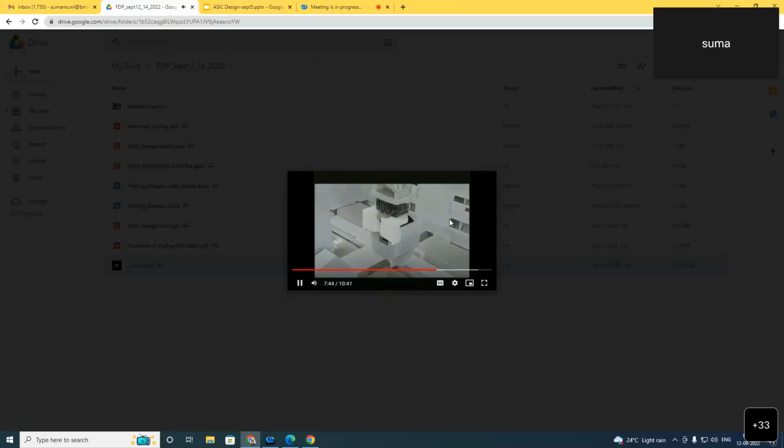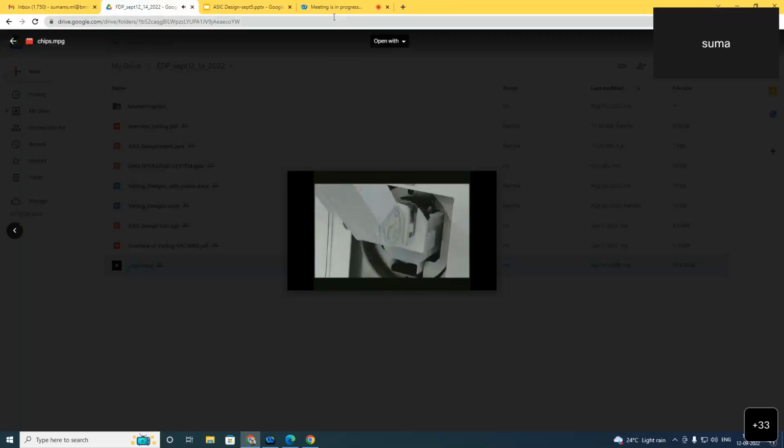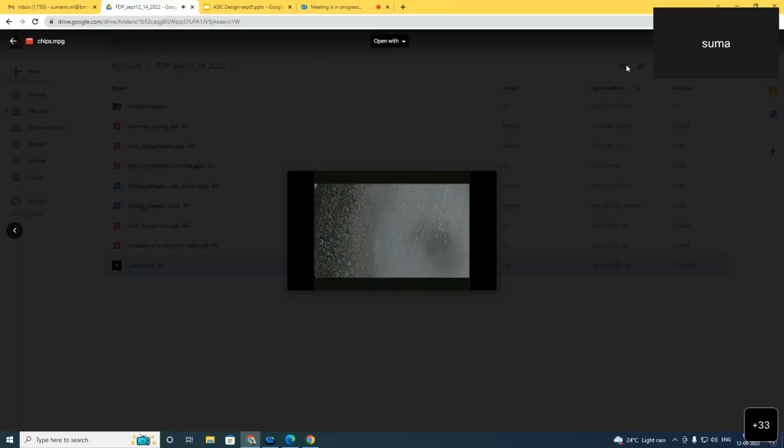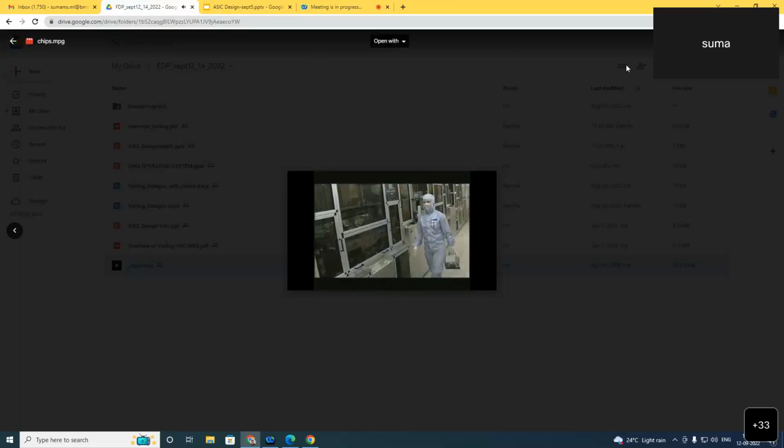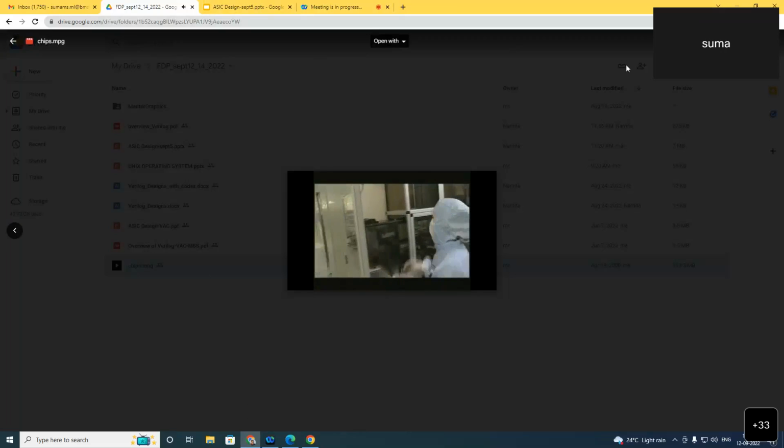One of the next steps in the process is etching, removing material locally from the slices with great accuracy. This department uses an automatically controlled process involving acids and caustics. Another technique used is dry etching with an etching gas.